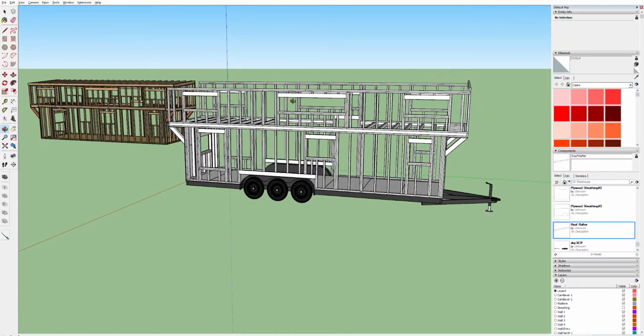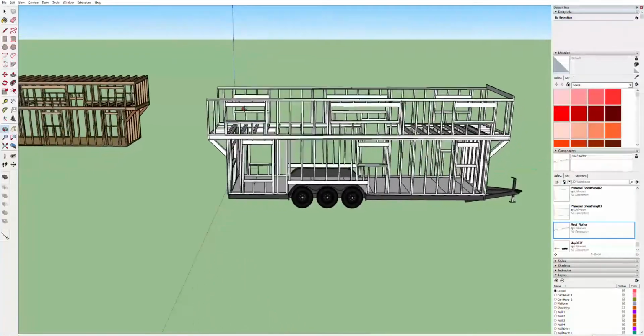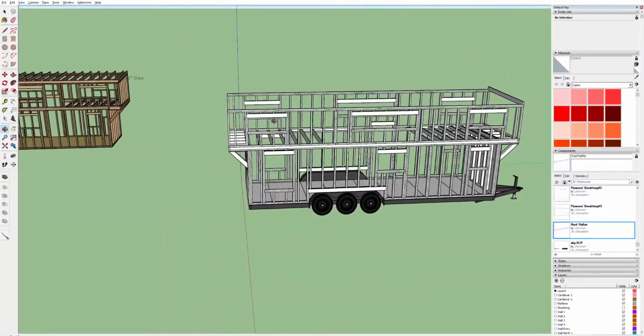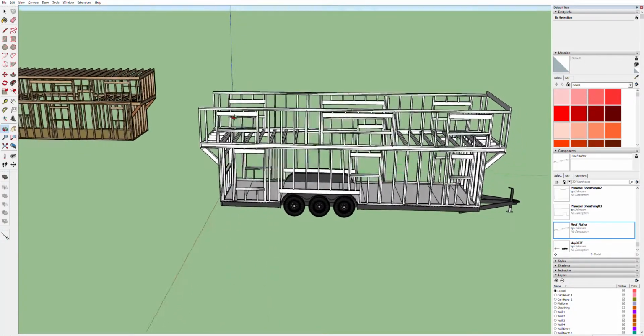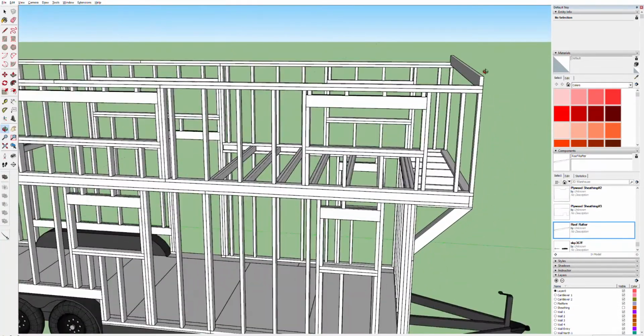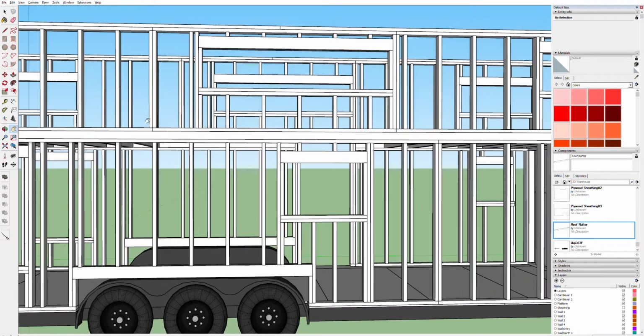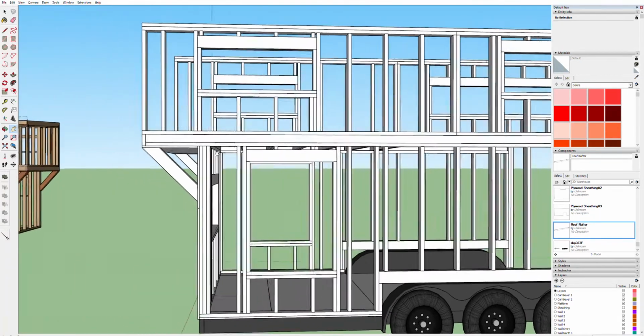I need a roof rafter at each end, and I also need it to match up to the 16 on center stud pattern. I want the load from the roof to go straight down. Like you see how all these 2x4s are stacked on top of each other. I want to land a roof rafter on top of each of these and go all the way straight down, so the weight from the roof is transferred all the way down to the trailer bed.